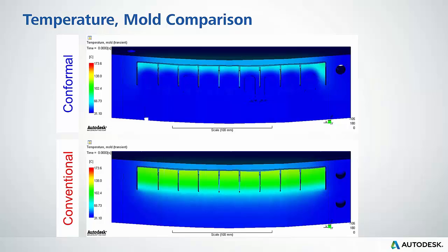So this is just one comparison between conventional and conformal on the top, and we see similar things, right, when we start applying conductive mold materials, copper alloys, right? We see this impact. Conformal cooling is just icing on the cake, if you will, or another approach, and sometimes we've got to be careful with the conductivity with this approach, right? It's easier to create cold spots as you move closer to the part surface with conductive materials such as copper alloys and aluminums.